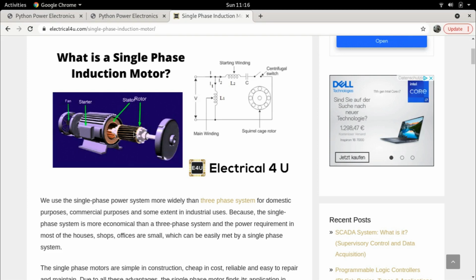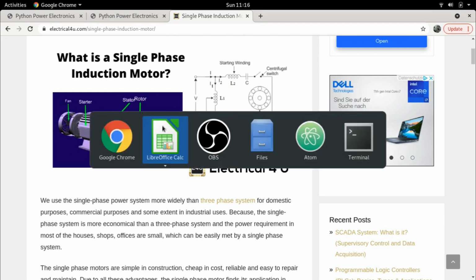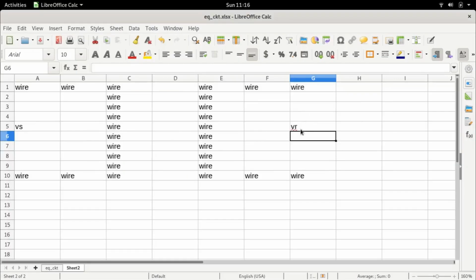Voltage will be applied in the specific case of a wound rotor induction motor, where the rotor consists of a winding similar to the stator, right? And this winding is usually accessible using slip rings, and you can apply a voltage to it. But in this specific case, there is nothing. But let us consider the general case where there could be such a voltage, and that voltage is VR, right?